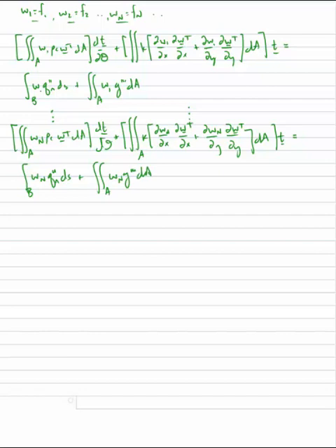So this now is n equations, right, 1 all the way to n, in my n unknown temperatures. And actually, if you think about what just this part of the system of equations looks like, you'll see that it starts to look like a capacitance matrix times d temperature d time.